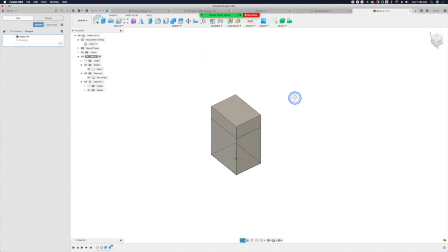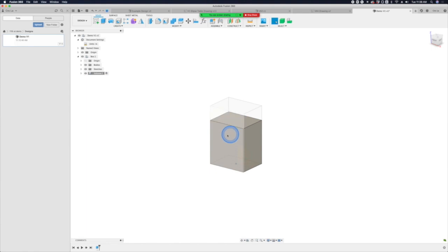This will let me show you the active components. Because we have two here, let me clean this up a little bit. Because this volume is inside this component, we can see them both. But if I activate this component, it grays out everything else around it. It makes it easier when you have a lot of complex shapes to keep things organized, like assemblies of parts. You'll put components inside components to allow you to isolate them.